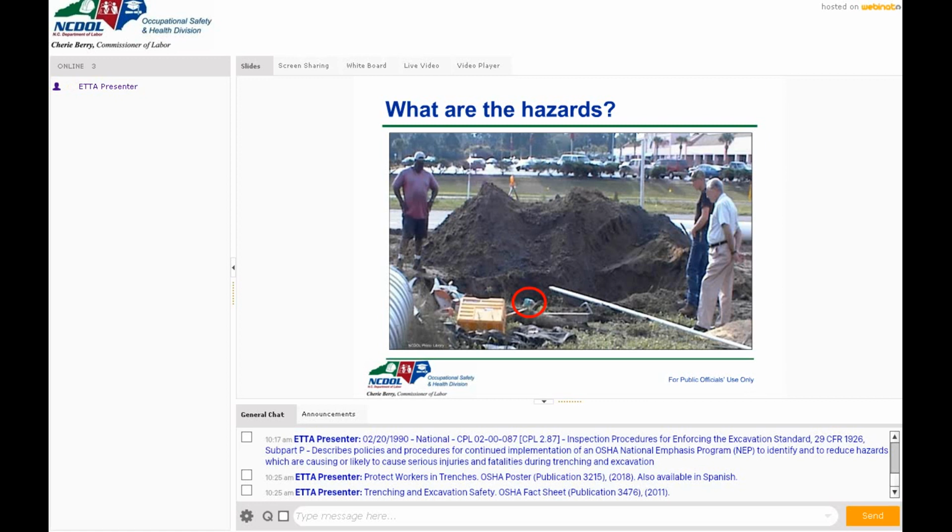Not just moved away. There's a specific thing. There we go. Mr. Steve got it. 2 feet. That includes material and everything else. Nothing can be within 2 feet of the excavation or trench site. You guys are on the ball.